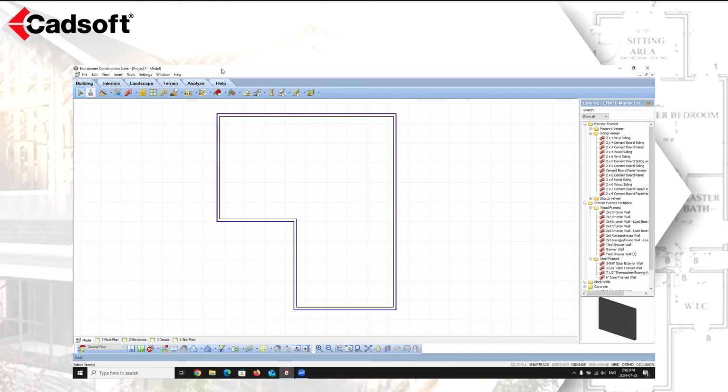We're going to be taking a look at creating our custom floors for this design that you can see here on my screen. So when you insert a floor using the structural floor by picking points tool, you can define the size and the shape of the floor as well as where the span starts and ends. So let's insert a floor manually and we're going to edit its properties.